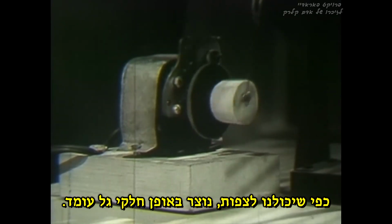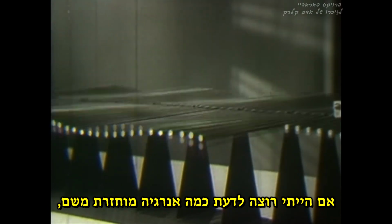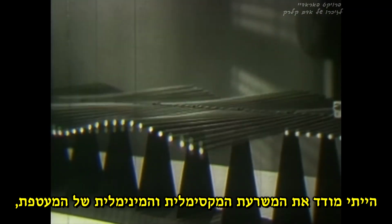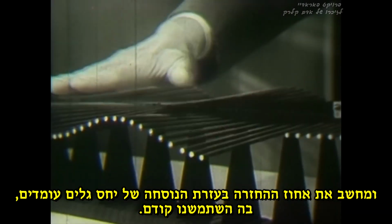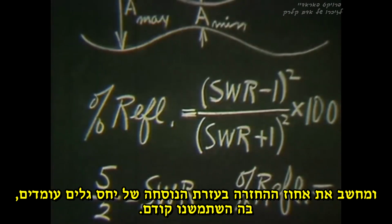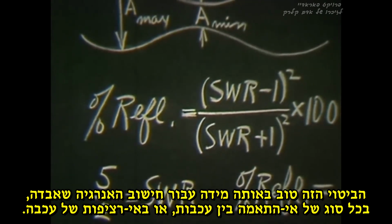As we might expect, a partial standing wave is produced. If I wanted to determine how much energy is reflected there, I could measure the maximum and minimum amplitudes of the envelope and calculate the percent reflection by the standing wave ratio method we used before. That expression is equally good for calculating the energy loss at any kind of impedance mismatch or discontinuity.